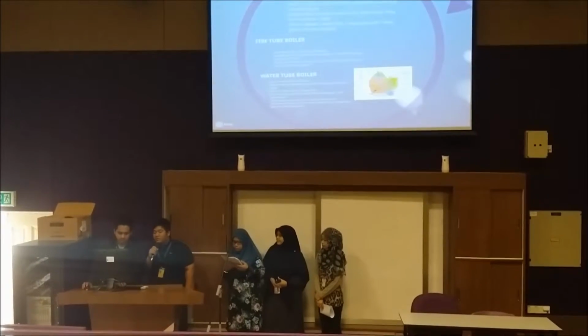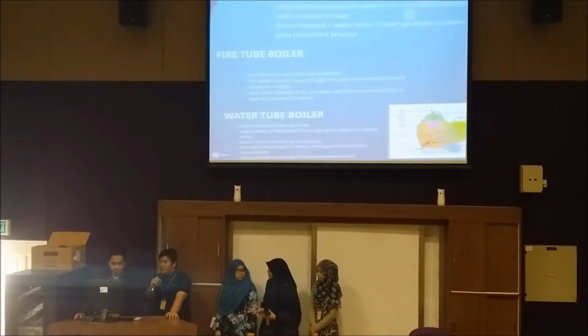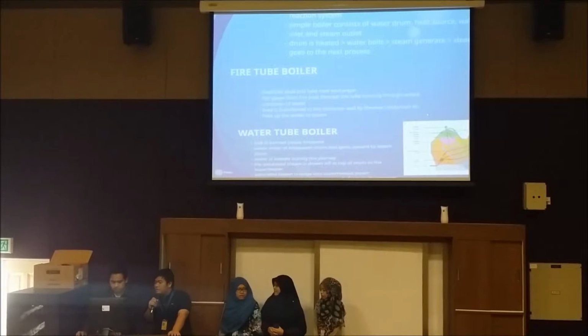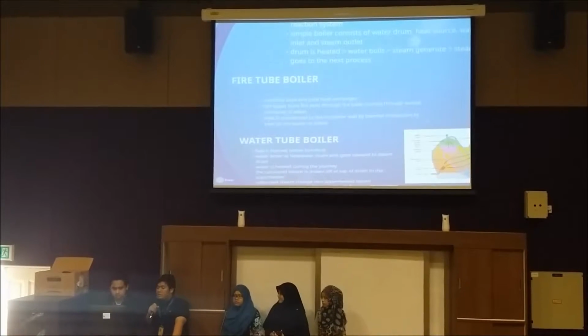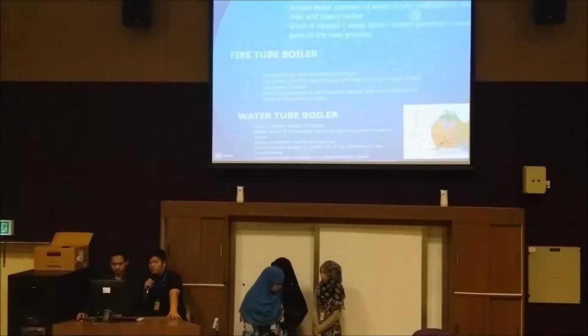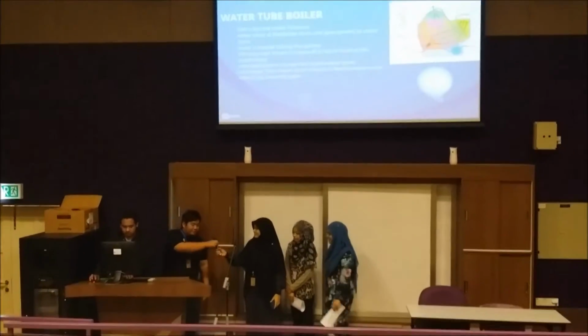For the fire tube boiler, it is a modified shell and tube heat exchanger. Hot gases from the fire pass through the tube, running through a sealed container of water. Heat is transferred to the container wall by thermal conduction to heat up the water to steam. Next, I proceed with Amy.